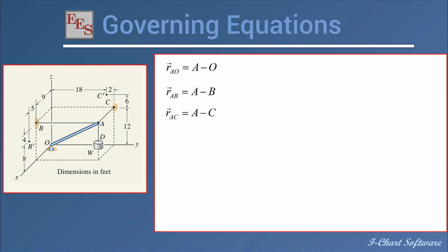Okay, so we're going to go ahead and solve this problem. It's actually a relatively easy problem to solve using a computer, and the reason is because we can start the process by setting some arbitrary value of W, and with that arbitrary value of W, it becomes very easy to calculate the forces in these members, and then we can just one by one figure out what value of W causes each of these members to fail. And of course then the value of W that's the smallest is the one that will cause the structure to fail. So let's go through and just derive the equations we need to program, and once we have those derived, we can enter them into EES.